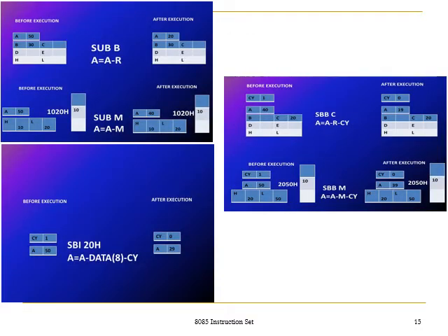Let's see the example of the subtraction operation. As we have stated, we can subtract a register from the accumulator, we can subtract memory from the accumulator, or we can subtract immediate data from the accumulator, or we can perform subtract with borrow with the content of the specified register or with memory. We are going to see all these, similar to ADD B, add immediate 8-bit data, add with memory, add with carry. Here it is subtract with borrow, subtract with memory.